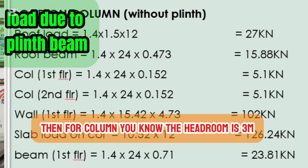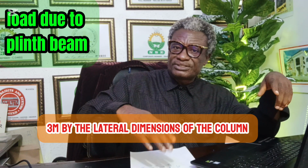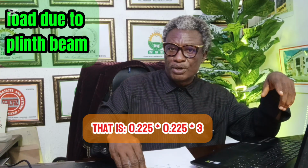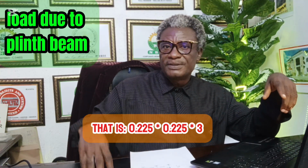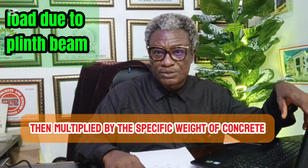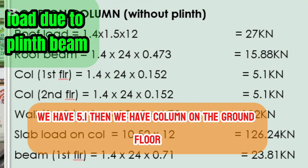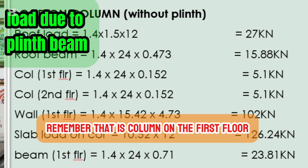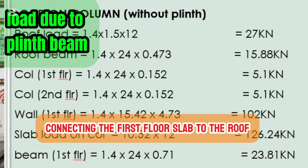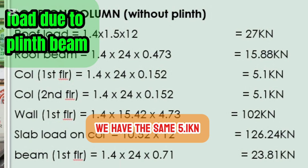Then for the column, the headroom is 3 meters. So we multiply that 3 meters by the lateral dimensions of the column, that's 0.225 times 0.225 times 3, then multiplied by the specific weight of concrete, which is 24. Then we multiply by the factor of safety. We have 5.1. Then we have the column on the first floor, connecting the first floor slab to the roof. Then we do the same for the column on the ground floor. We have the same 5.1 kilonewtons. Then for the wall,